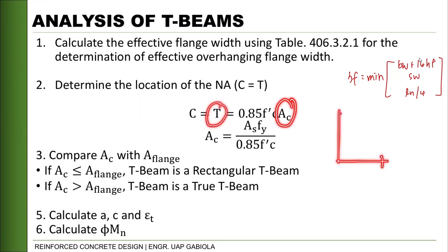T is basically our reinforcement multiplied by our stress para makuha natin yung load. So, load times area. Yes, stress times area para makuha natin yung load. So, that is As Fy. Equating both sides, dividing both sides by 0.85 f'c b, we will get the value of Ac.